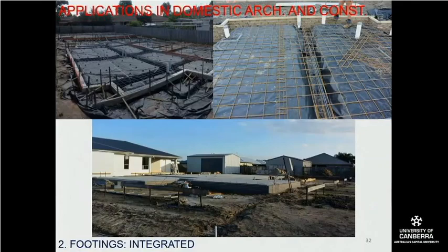This is a few pictures of that kind of thing, where you've got the prepared site with your plastic and your reinforcing. You see these little things here. These little hats are really what the reinforcing sits on. So in this picture here, they haven't yet put in those little hats, those little stands. And of course, what you need to do is to get the reinforcing bars off the plastic so that the resultant piece of reinforced concrete will act as a whole, and so the concrete will move with the steel, and the steel won't pop out of it.